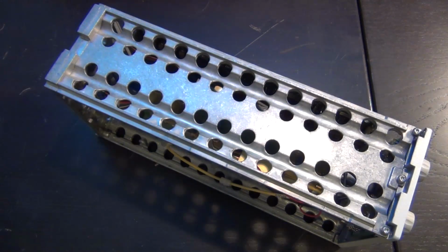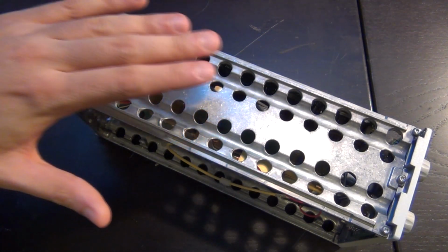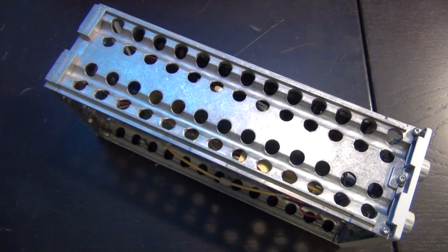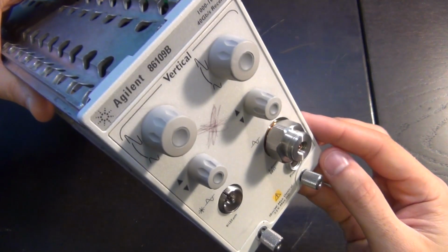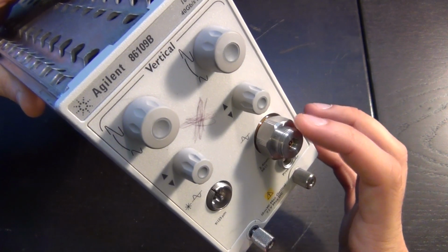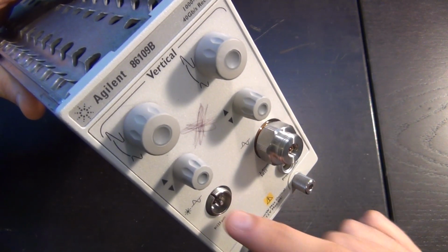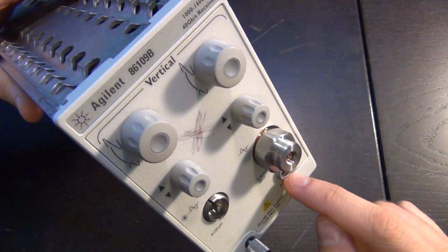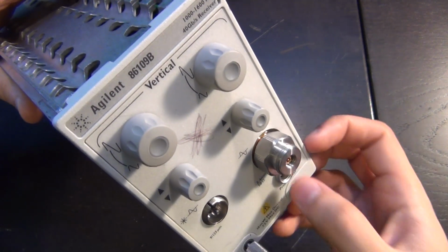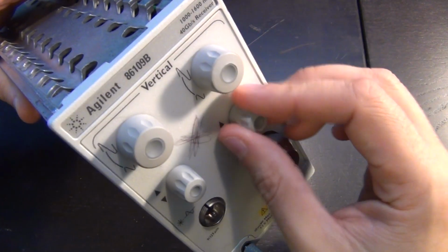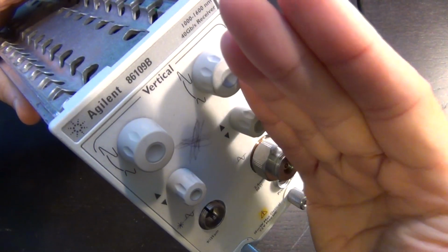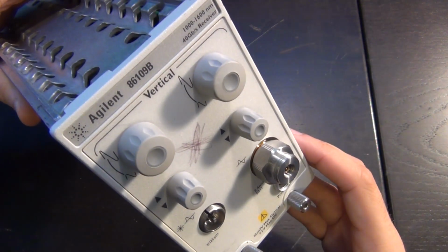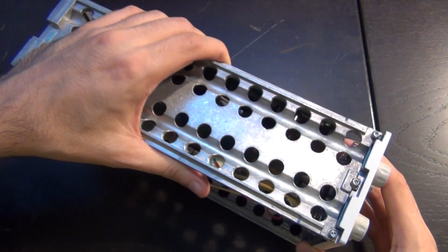Alright, now that we understand how this subsampling oscilloscope actually works and what components to expect in the module here, we can take it apart and take a look inside. Now, I don't think I went through it carefully enough in the front. Just to show you again, we have our analog input, 50 gigahertz bandwidth, optically modulated 50 gigahertz bandwidth. There's a probe power at the front, which you can use for external probes and so on. And then you have vertical adjustments, just like you would have on a regular oscilloscope. So this is like channel 1, this is like channel 2 of a traditional oscilloscope. So there's no difference from that perspective.